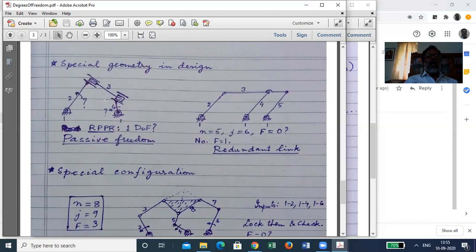And the way these prismatic pairs are organized, even without any motion of link 2 or link 4, link 3 can actually exercise its own freedom as it wishes, just going in the 2 slots up and down.